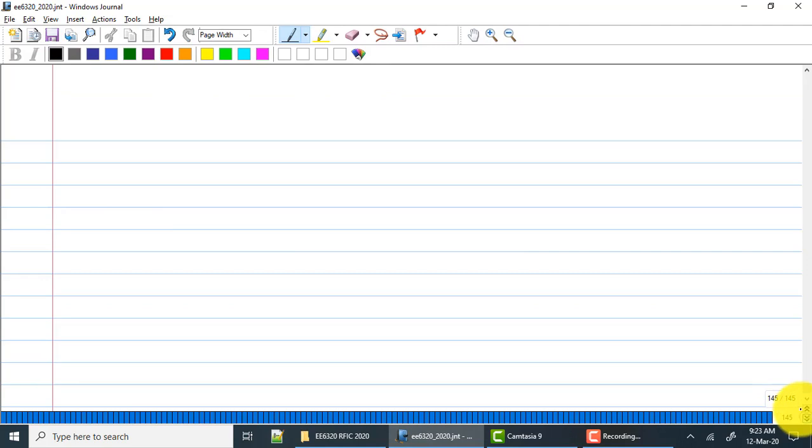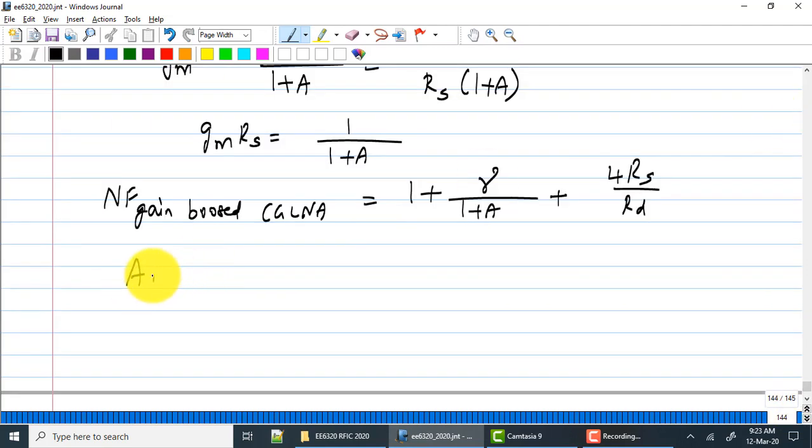And if you try to build a low noise A, then a couple of things will happen. First of all, you have assumed that A has infinite input impedance. It will most probably have a capacitive input impedance, and that will shift the input impedance. If you try to choose, let us say, a low noise amplifier, what kind of choices would you make for A?